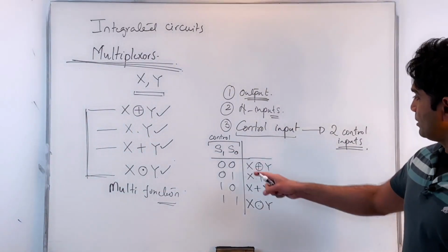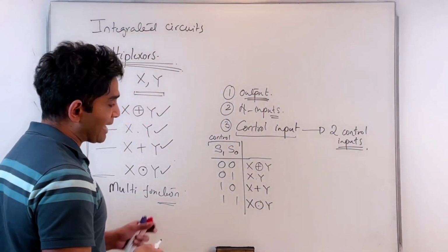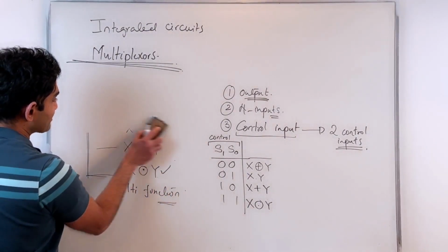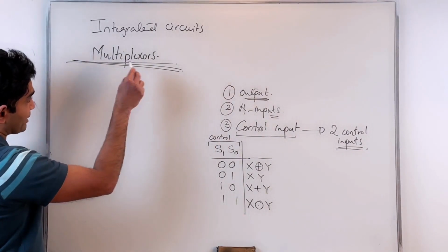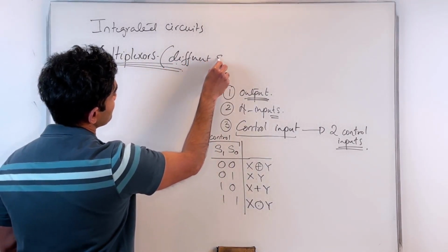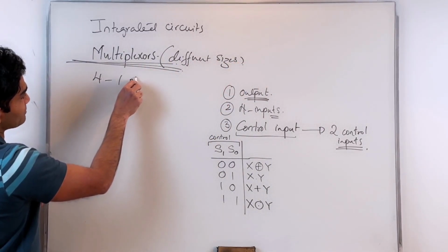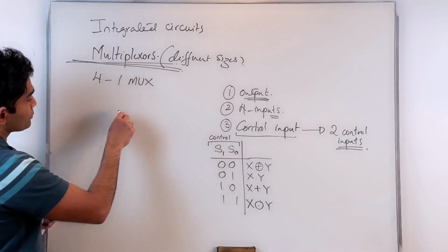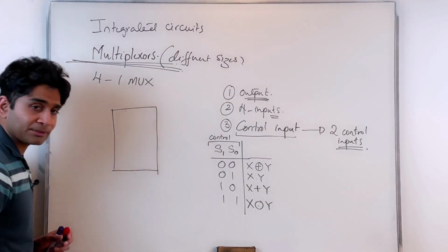So now how do I design the hardware? Okay. Now it turns out that the multiplexer exactly does this for us. So what is the multiplexer then? It's basically a piece of hardware. Again, it comes in different sizes. So let's say I'm trying to describe a 4-to-1 multiplexer. In short, we can call a multiplexer a mux. Okay, a 4-to-1 mux. So what you have is basically four inputs, and you can multiplex among those four inputs.